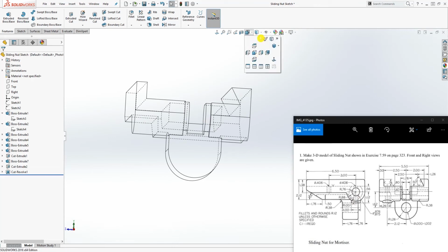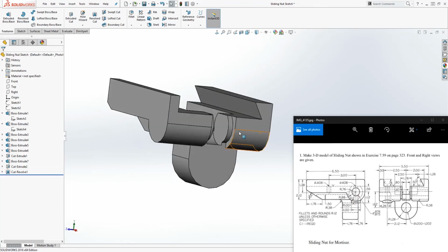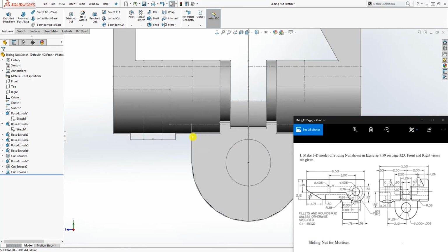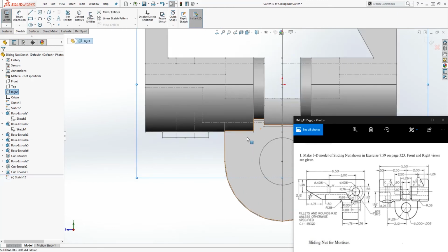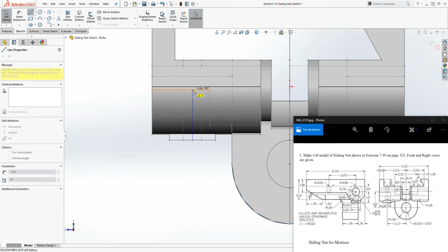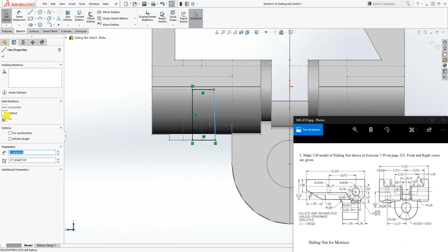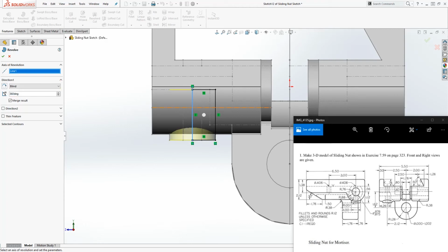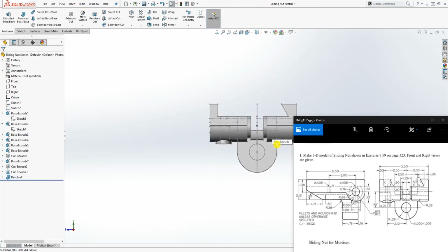So we are pretty much almost done. The other part is like the minor part. We just gotta fill everything in. So I'm going to show my sketch again and show this sketch, number 2, and now we want to add this. So again, on the right plane, sketch, and we're just going to draw a line. This is the midpoint where I have this point. I can just draw a line going up, coming down to this point and to that point. I'll make sure this line is vertical, and feature, revolve about this point, and we are done with that.